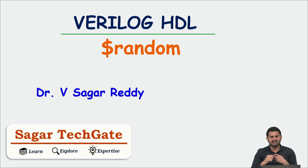So $random is for quick and simple random values, but with care for negatives, whereas $urandom_range is for when you need clean and bounded positive values in a SystemVerilog testbench. We prefer this $urandom_range. Thank you very much.